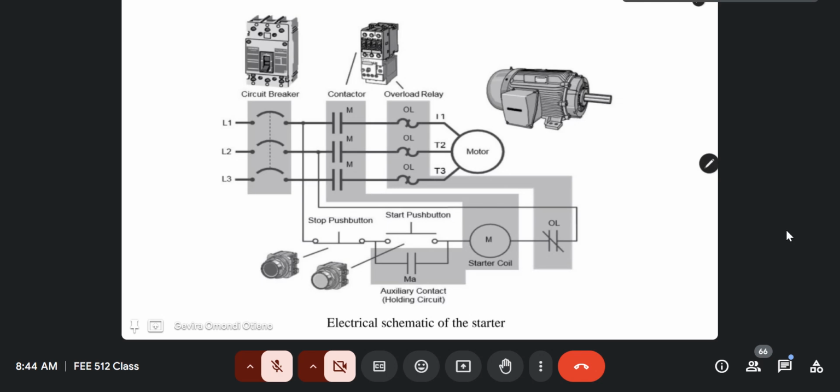So you know that in your ladder diagram, you can identify input devices and output devices. For example, the input field devices here should be easy to identify from the schematic itself. We had done this previously, and we said that these input devices could be push buttons. In this case, we have a stop push button. The stop push button is going to be an input field device, meaning we'll need either a normally open contact or a normally closed contact to represent this button. We also have the start push button.